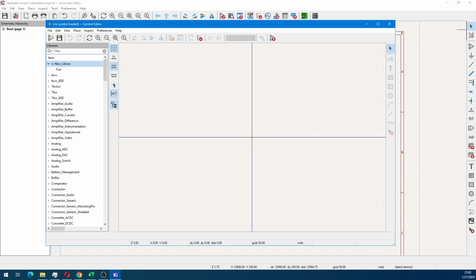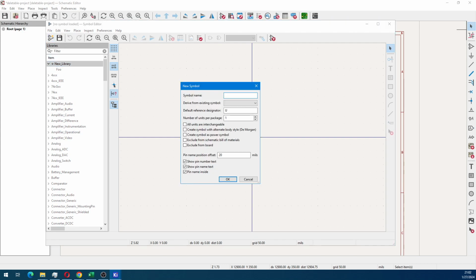So at this point, let's add that second component. So what I'm going to do is first highlight the name of this custom library. That will instruct KiCad that you would like to add to that library in particular. There used to be a different mechanism for that one, but it was, I think, pretty confusing. And let's create a new part.